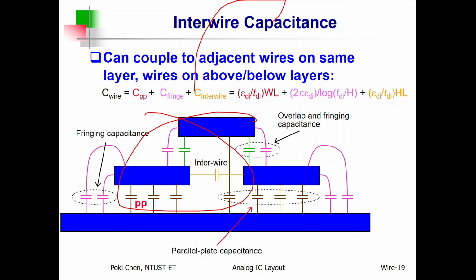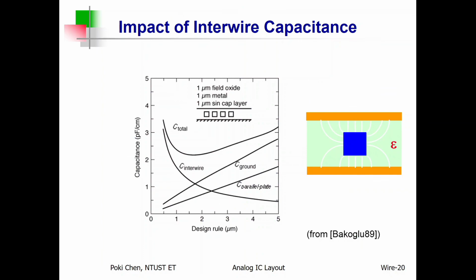As neat as possible. Then we can reduce the parasitic capacitance between them, among them, very much. As I mentioned moments ago, for each metal layer, you have something below you, you have something above you. You need to consider all of them: the parallel plate capacitance and the fringing field, all of them. So if you would like, you can do such kind of simulation. Calculation by hand is totally impossible. That is too complicated and time wasting, so it depends on our EDA tools very much.